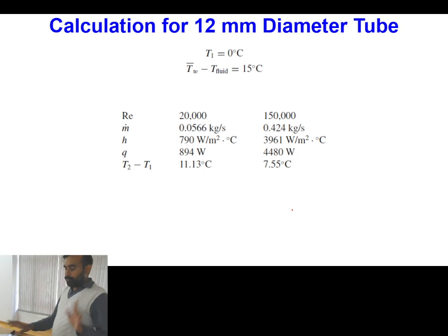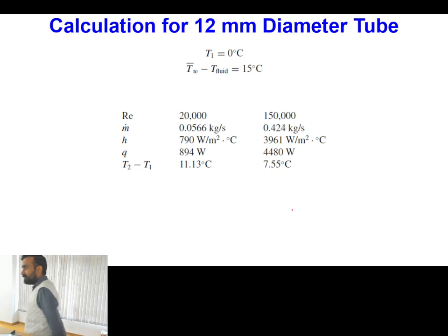Okay, so previously I told you about the ranges we are obtaining, particularly for mass flow rate. Yes. Sir, how will we select a device for experimental values? Whatever flow meters and thermocouples we are using, they are selected based on theoretical values, but it may happen that the experimental values exceed them. Yes. So for how much greater a range should the device be selected?